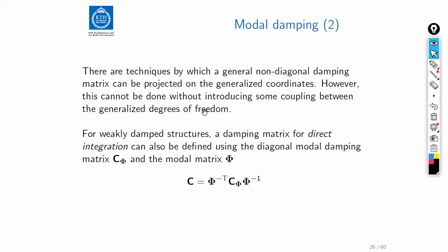Modal damping can also be used if you have a little bit more freedom, if you are not totally forced to use this commercial code, if you are doing a little bit of programming of your own. The concept of modal damping can be transferred to problems in the time domain where we might want to use direct integration, perhaps because we want to introduce some small nonlinear aspect or something like that. So we need a damping matrix that corresponds to the modal damping that we have ascribed from the standard.